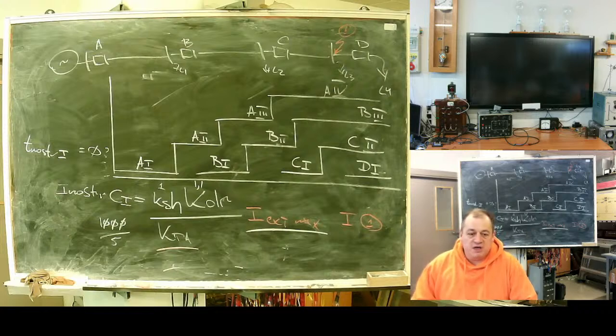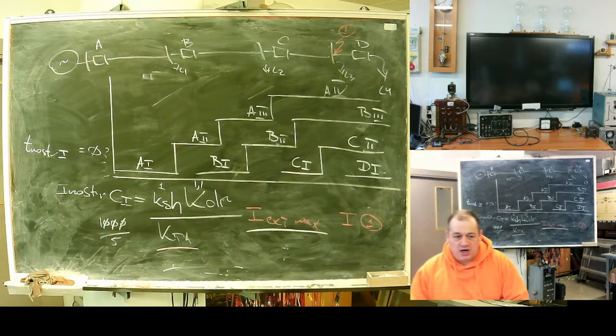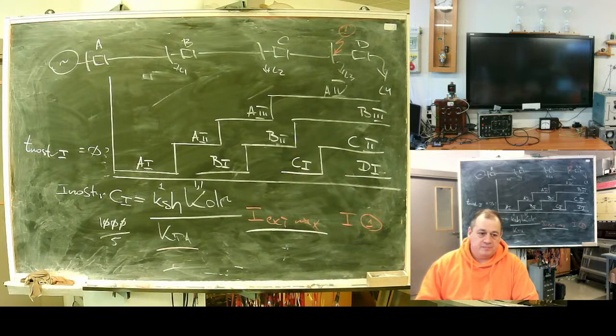What does this mean? 50 is very good. The digit is 100 milliseconds. Do not set operation time of the first zone to zero. Leave some small space. Okay, if you are in a rush, write 50 milliseconds, but leave some space for surge arresters. Understood?